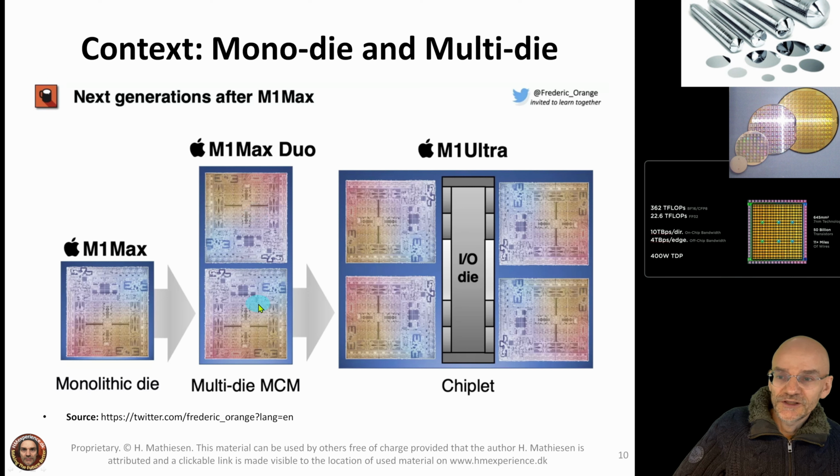So if you build an entire wafer with one big die, then the probability that there would be an error in that wafer scale die would be 100%. There will definitely be one error, and then there will be several errors somewhere on that die. If there's just a single error, a single transistor that isn't built correctly so it doesn't function, then you have to throw out everything you have built, and that will increase the cost. So the smaller the die you have, the less the probability that you'll have to throw out the chip because of an error on that die.